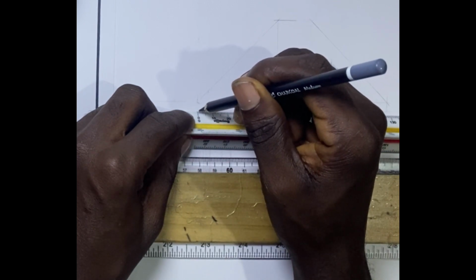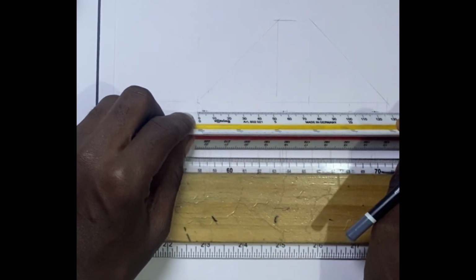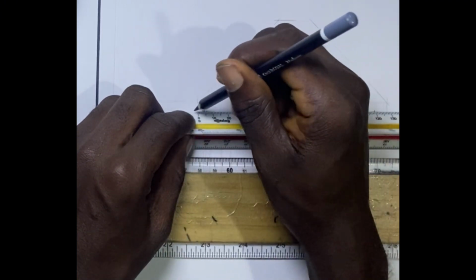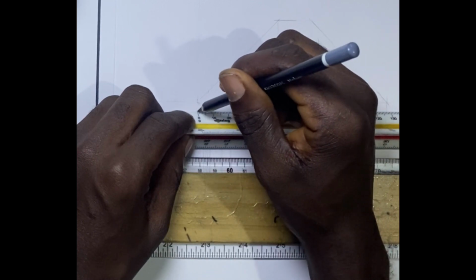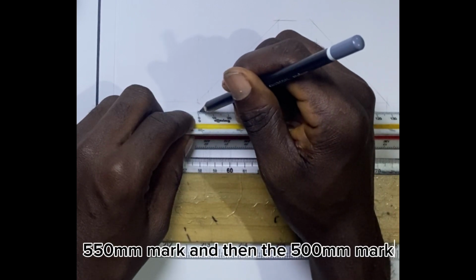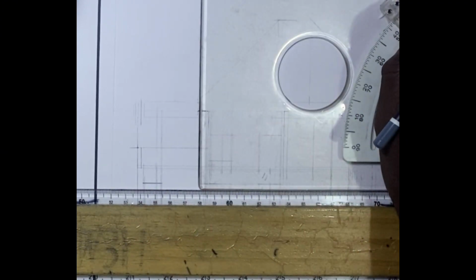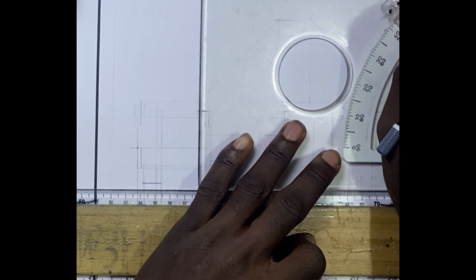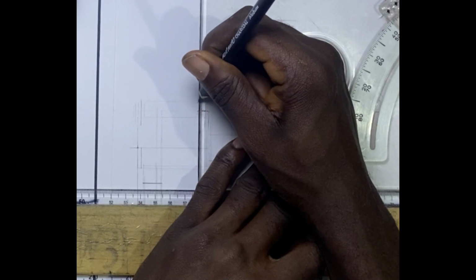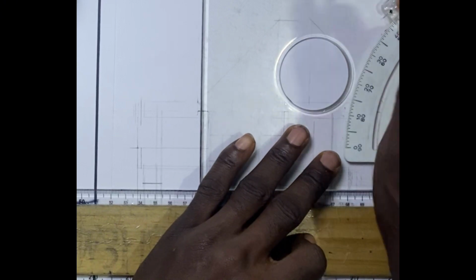and then at the far edge of our fascia board, the other time I said our fascia board is 600 eaves projection. Its eaves projection is 600, so we take another 50 inward at the 550 mark, then the 500 mark. Alright, so with that being done, I then have the design I want for my fascia concrete.